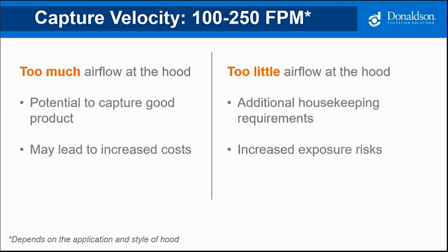As I mentioned, too much air can be a problem. It'll capture the gas. It will lead to an increase in cost. Too little air would mean I have fugitive dust floating around the plant. We have additional housekeeping that we have to deal with. Plus, I'm exposing my employees to the weld fume as it's being generated.